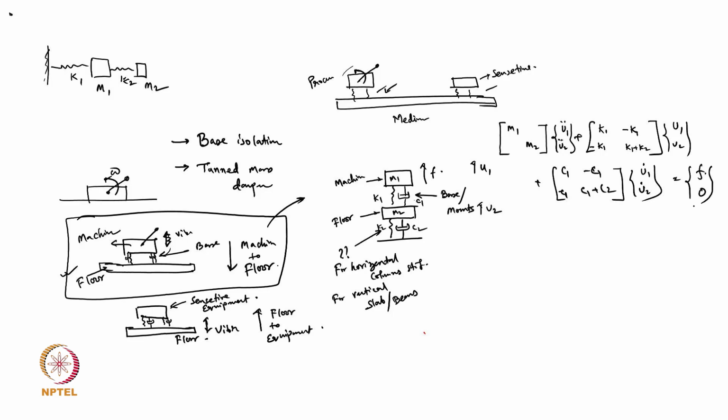Can I write the equation of motion like that? First I put the mass matrix m1, m2 with u1 double dot and u2 double dot in sequence. Then I put k1, minus k1, minus k1, k1, and as the third degree of freedom is fixed, k2 cannot be written completely, so that is k2, and then minus k2, minus k2, k2 will be cancelled out.